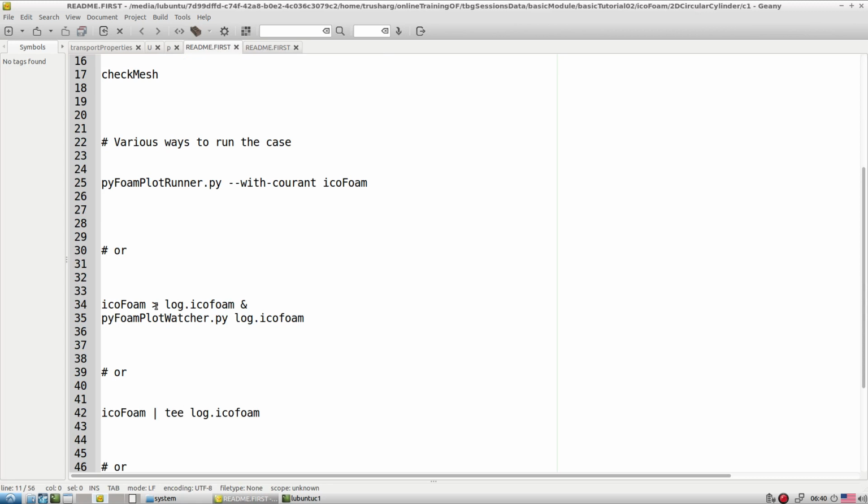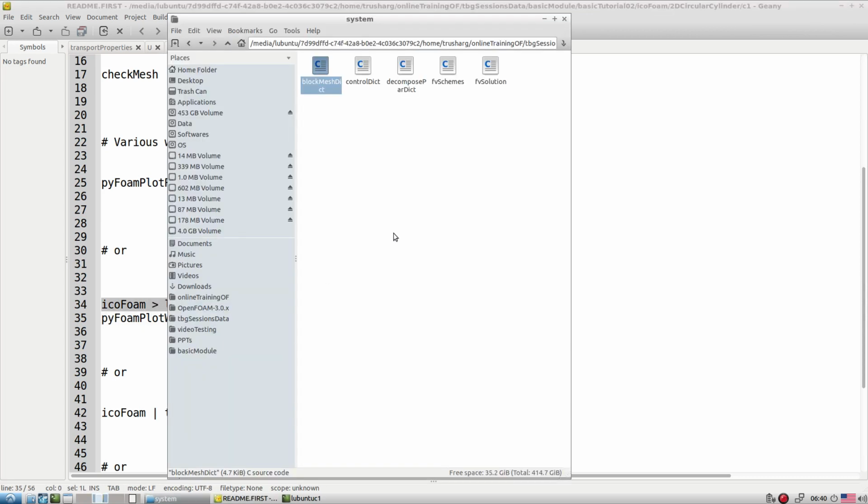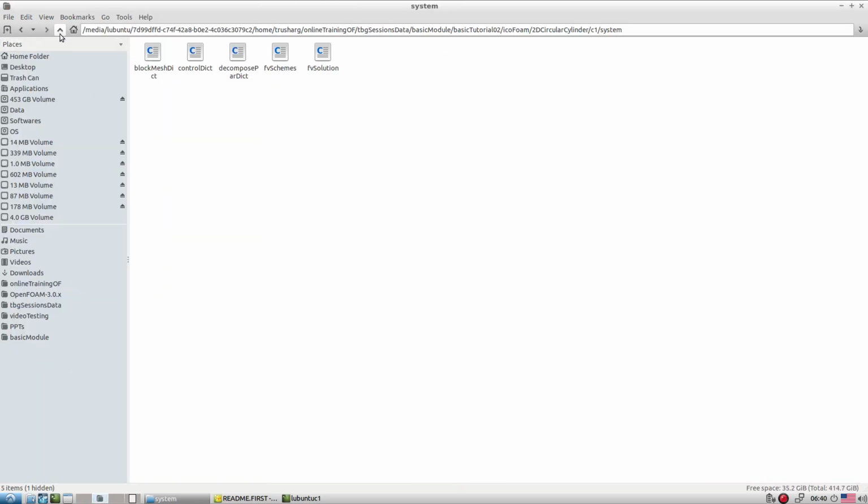Okay, so for running the case, we are going to utilize OpenFOAM. Before we start the simulation, we make sure that we are setting all the properties correctly. So we want to run for Re equal to, let me check, 250. Yes, Re equal to 250 we want to run, and our cylinder diameter is 1 meter.